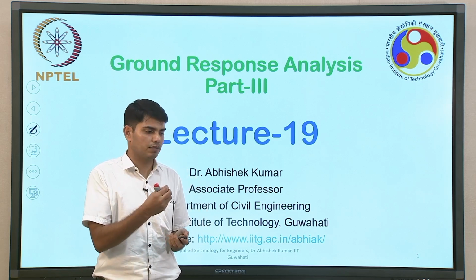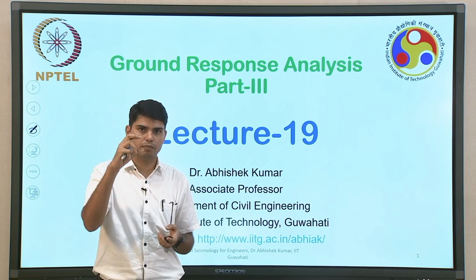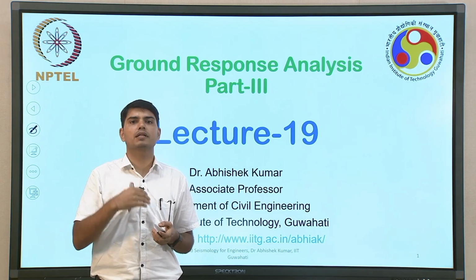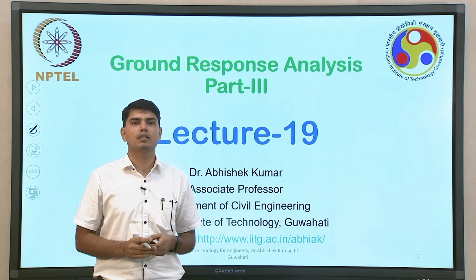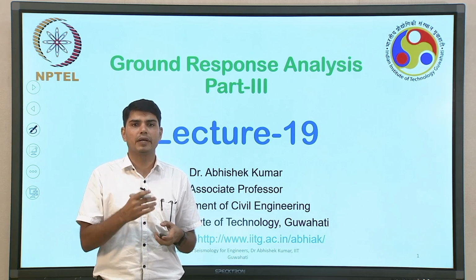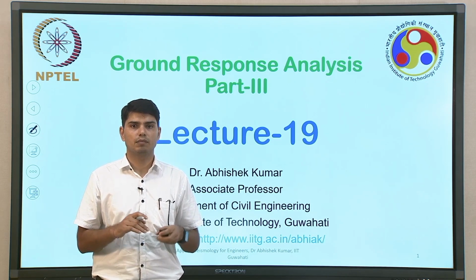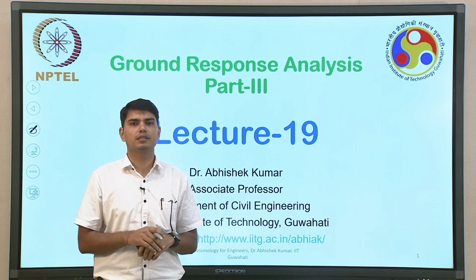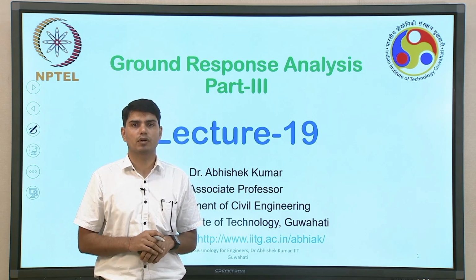Then we discussed that whenever we are talking about soil, it will not be only one soil layer available at the ground surface, but a number of layers. So, depending upon the known conditions, we have to take into account the compatibility equations: displacement compatibility and strain compatibility. Thirdly, we discussed that the resistance soil is going to offer to any external loading will be dominated by two parameters. If we refer to Kelvin-Voigt solids, where both the damper and the spring are attached in series, then the response of the soil will be approximated by KV solids, or Kelvin-Voigt solids.